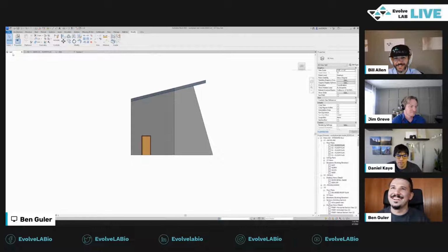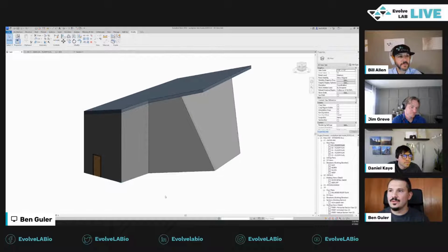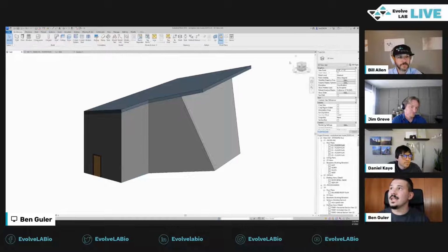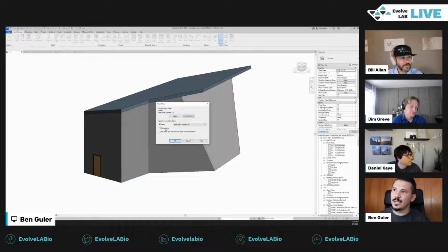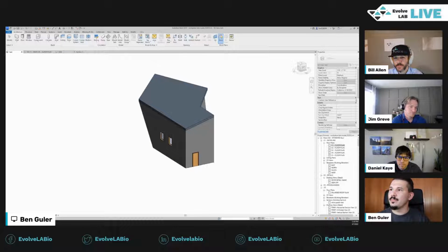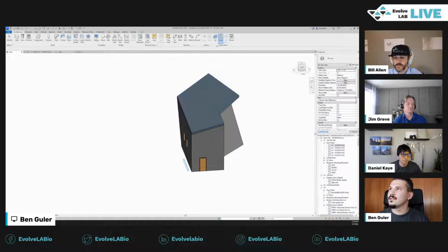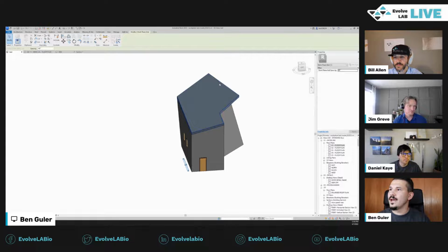2024. There you go. Let me go back to, actually I'm on the 3D view, but I locked it. So here's a non-3D view. Let me unlock that real quick. I've already showed that in the Revit 2022 version, but now they've also added a set plane over here, pick plane. So you don't have to click set plane and then pick plane. You could just do that with one button, which is really cool. So if I click this, I could just click my plane, and then it will update to that.